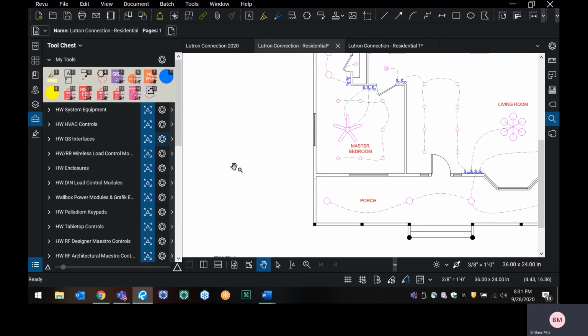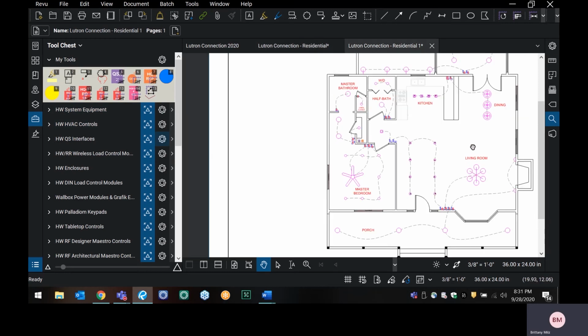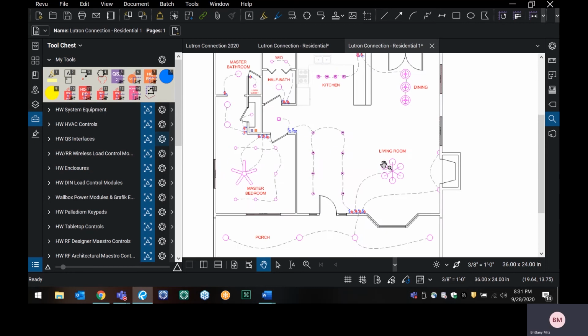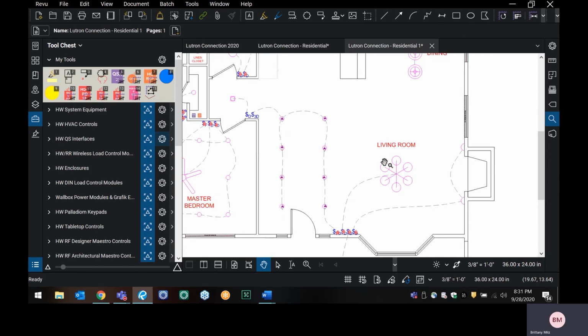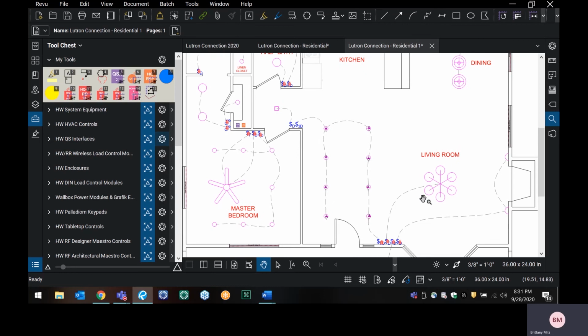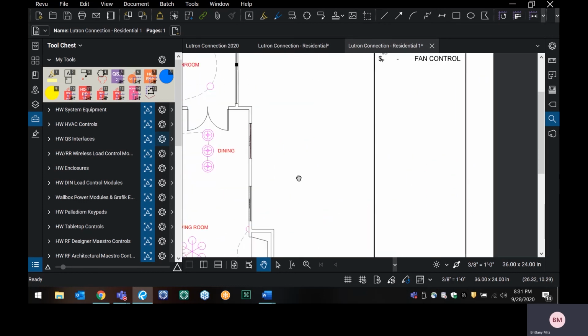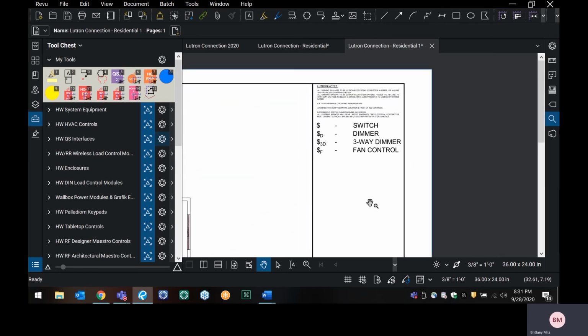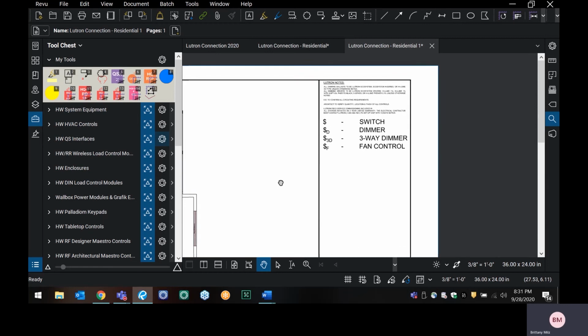So now we're going to move into stamping some product onto our floor plan. Now I'm just going to switch my screen here a little bit, as I have actually placed some items on my drawing here for this training. Now there are a few different ways to approach stamping product. So for one, you can place the product individually based on the legend that's given on your floor plan. So if we just pull over here, this is my legend that's given on my floor plan.